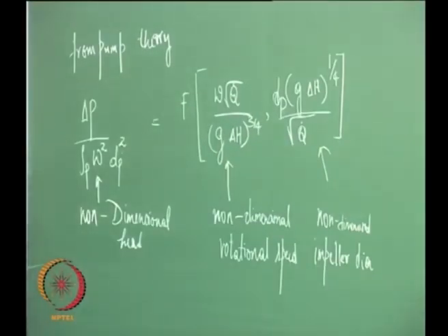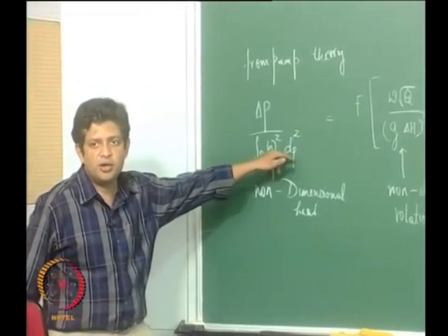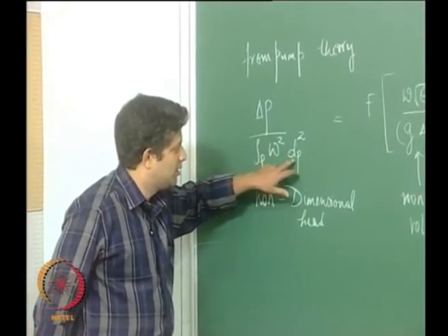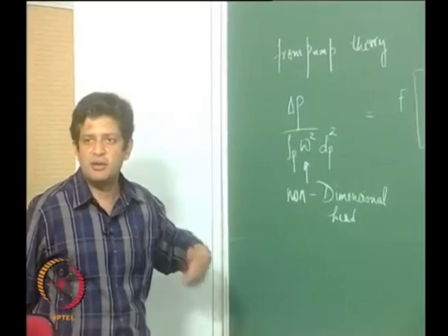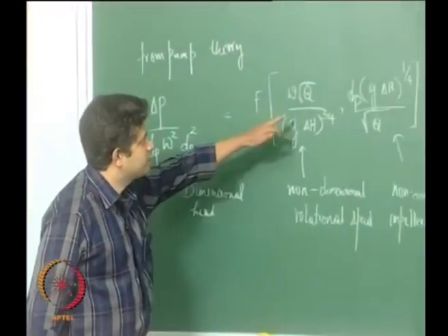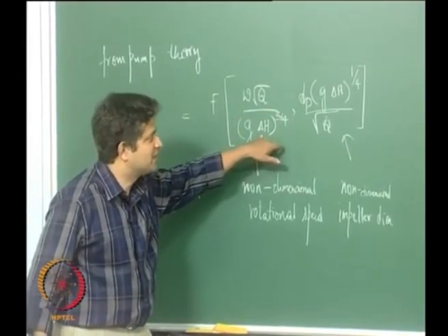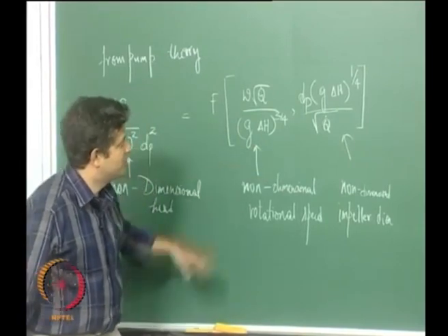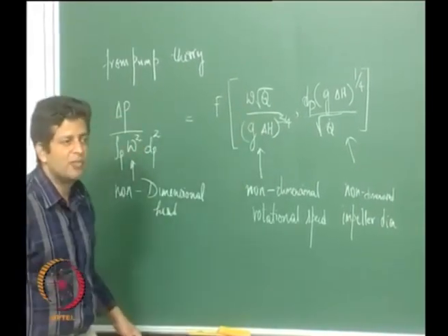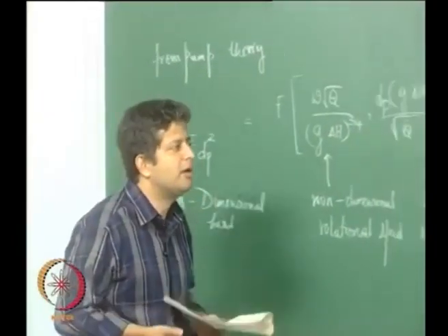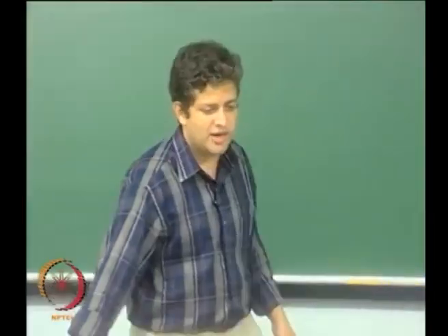Now if you see here, this comes from Buckingham pi theorem, which you must have studied sometime in your undergraduation. The rho p here corresponds to the density of the fluid, omega corresponds to the rotational speed in rpm, and dp corresponds to the diameter of the impeller, okay, and q dot is the flow rate and delta h is the actual head rise, okay. G is acceleration due to gravity. Now if you have this, then you can plot it as shown here in this figure.